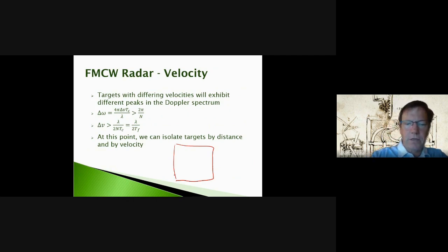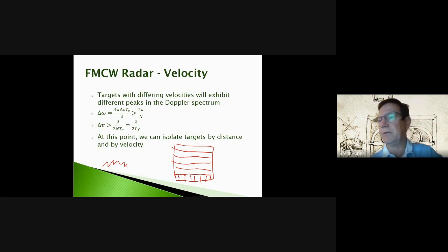We're going to take these signals and perform an FFT, and we're going to store complex values in each of these frequency bins associated with this fast Fourier transform, right? And so these are all complex values. We can read out the magnitude or we can read out the phase, right? Then we're going to send another pulse, do that again, collect up a frame of that information, and keep doing that.